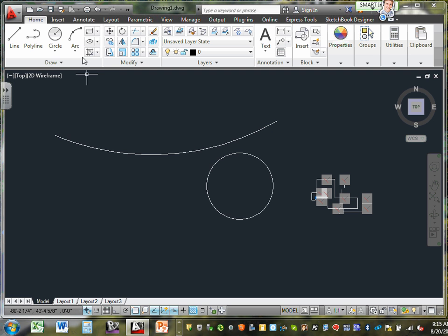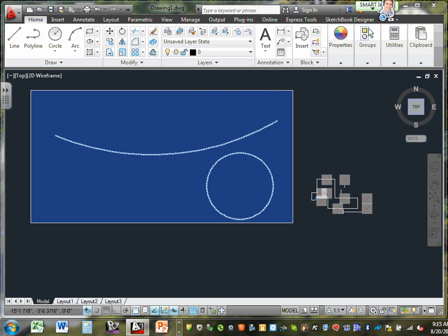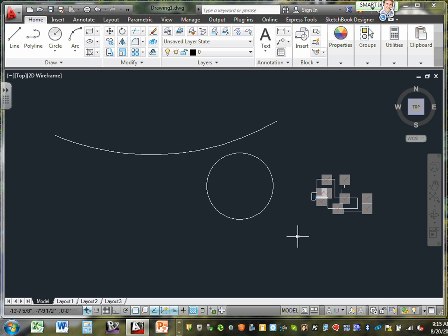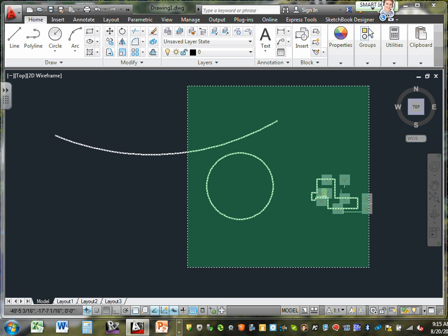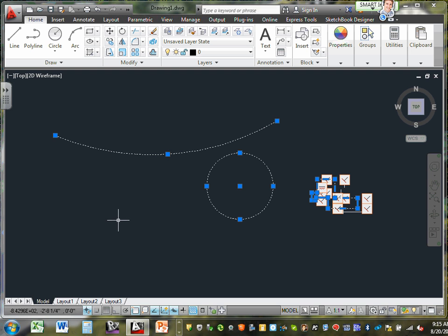If you want to select them together, all of them, box them in. One way of doing it: anything, if you come from right to left, anything you touch, you select. Left to right, anything you box in, you select.